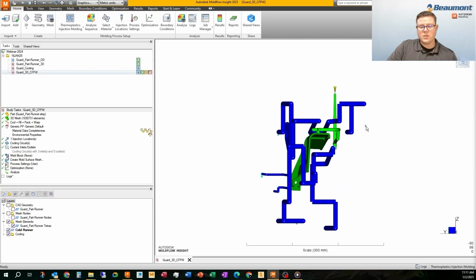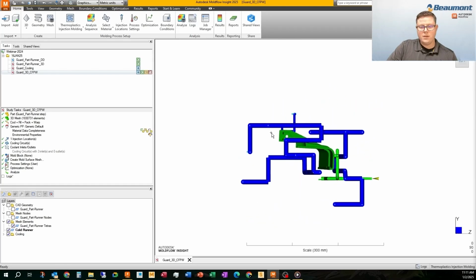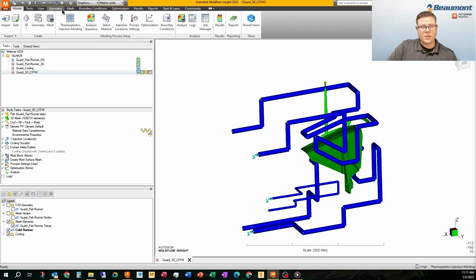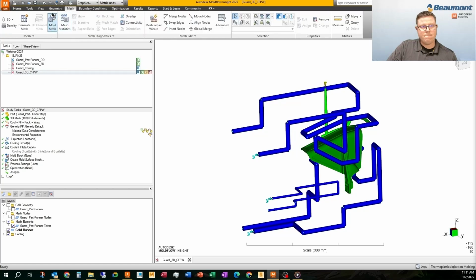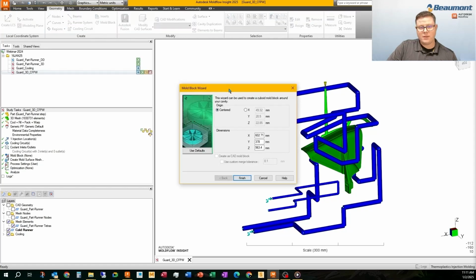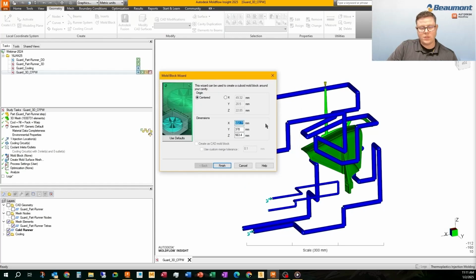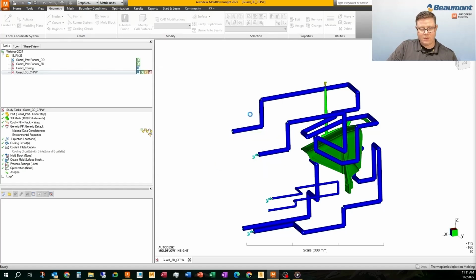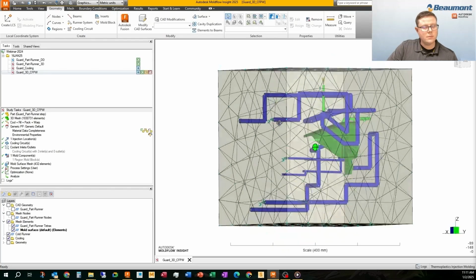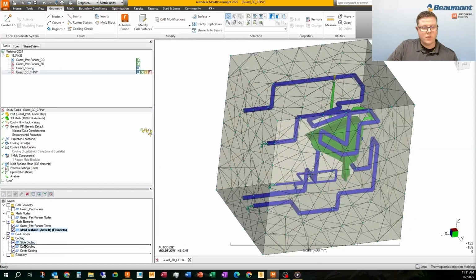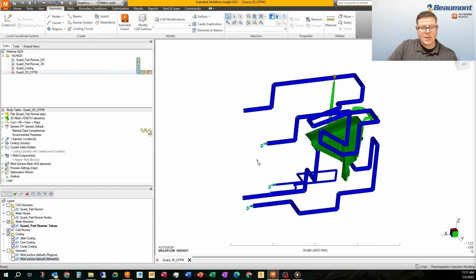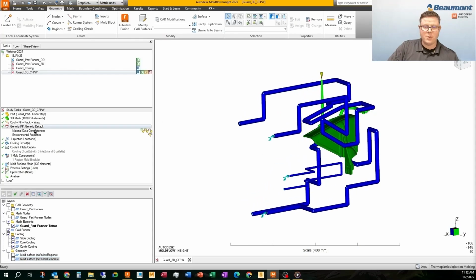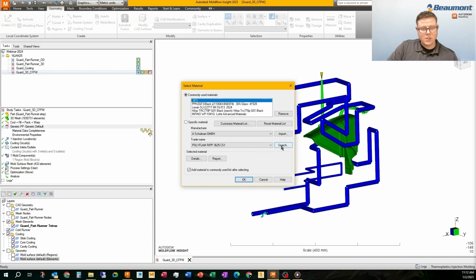And what I'm doing is I'm using the scale down below to get a mold boundary. So I switch to the geometry tab, grab my mold block wizard, and by using that scale, X direction 350, Y 300, and Z 350 millimeters. I like to move those elements down under my geometry layer. I'm able to turn on and off that mold boundary.